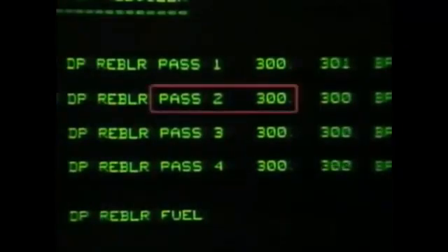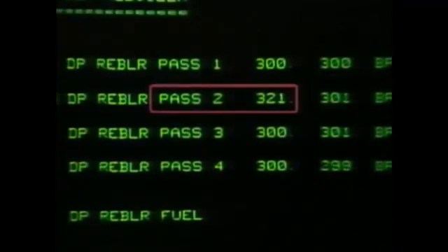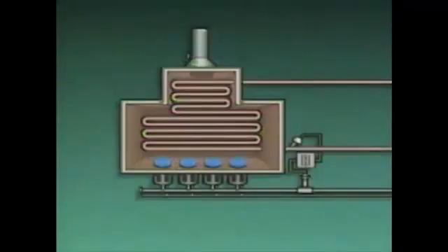If reduced process fluid flow causes a hot spot, increasing the flow rate through the affected tube often works. If there's more fluid moving through the tube, it will carry away more heat. Another way to handle a hot spot is to reduce the firing at that area in the furnace. If the burner closest to the hot spot is turned off, you'll direct less heat toward the problem tube.